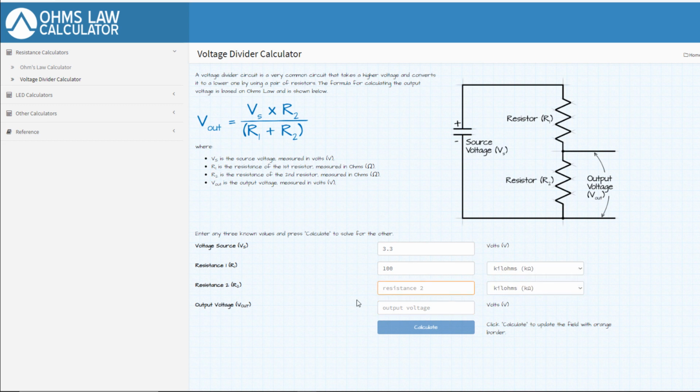You need to know two resistances of your LDR, that is the resistance of the LDR at zero light intensity and the resistance of your LDR at maximum light intensity. Either you can find these details in the datasheet of the LDR that you buy, or you can find this by manually testing it. Just use the probes of your multimeter across the terminals of your LDR and then try shining light on it. In my case, the LDR's resistance at maximum light intensity was approximately 30 kilo ohms.